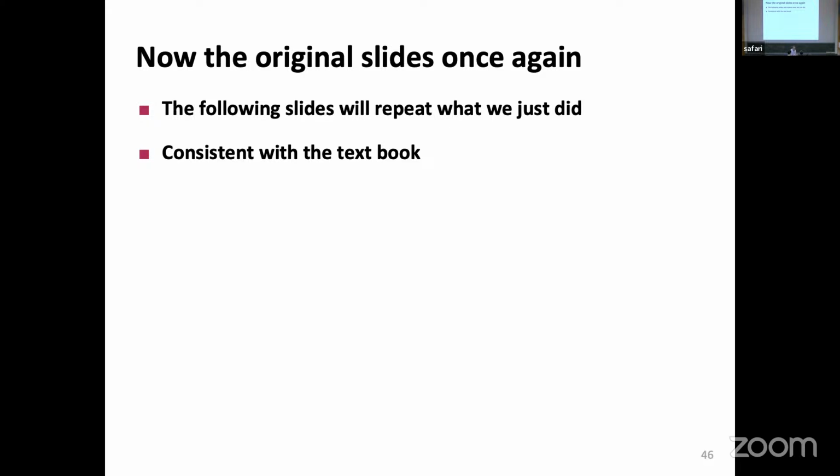At the same time, you realize that since the memory is not as fast as the processor, whenever I connect the data memory to a processor, I need to make sure that when I want something, the memory says, hey, the data is here. So there is a bit of handshaking agreement between them. I'm not throwing them in because I'm assuming implicitly that whenever I present an address, the data is here. In real life, in bigger systems, this never is the case.